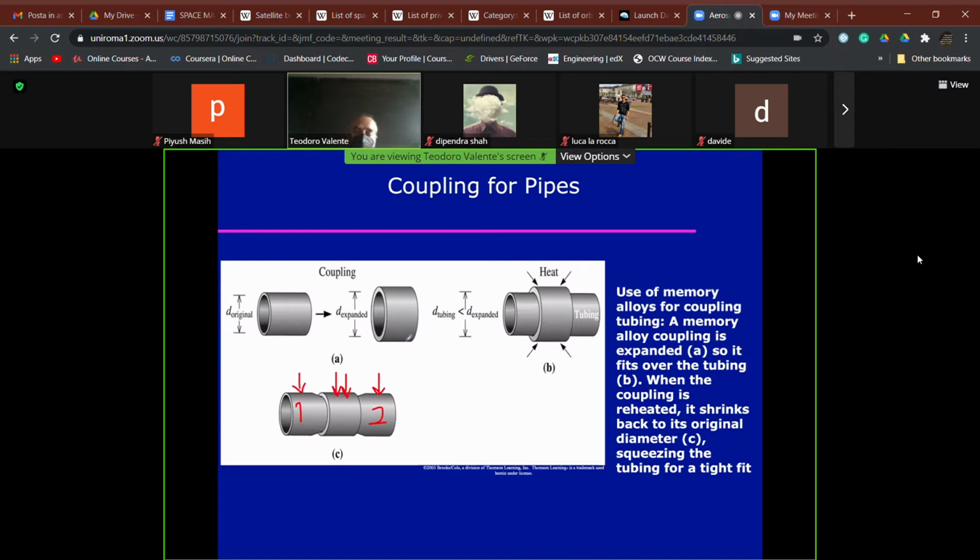Then we activate the shape memory alloy behavior, for example by heating, because remember that to transform austenite to martensite we need to cool, and when we want to recover the original shape and size, which was fixed in the austenite phase, we need to heat. We are now able to model the heating and cooling phase also with the general equation we have seen before.